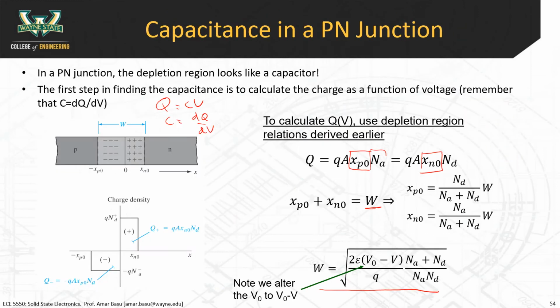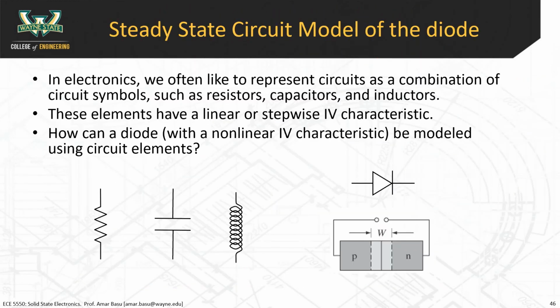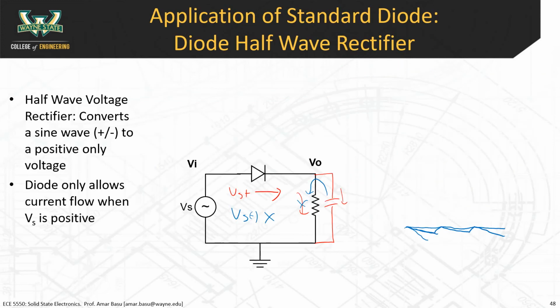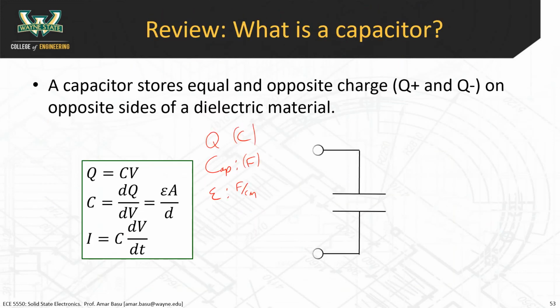And if we start talking about the models that we did earlier, before we said here that these are the circuit models for a diode. And so the appropriate thing to do in transient type cases is that you may also want to include this capacitance there as well, because the capacitance will impact the transient behavior of the diode. So what we did right now is we basically just calculated the capacitance of the junction.